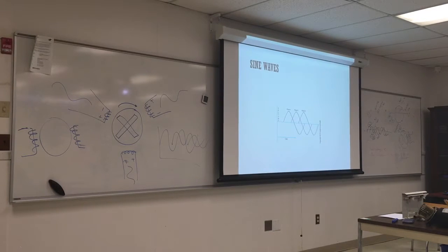What about three phase 220? What are you going to have? Three hot legs. Each one of them will be hot. If you go into a circuit breaker panel, the hot legs usually have what on them? A fuse. If you see a fuse or a breaker on the line, that's a hot leg. You do not want to put safety switches, fuses or circuit breakers on a neutral.